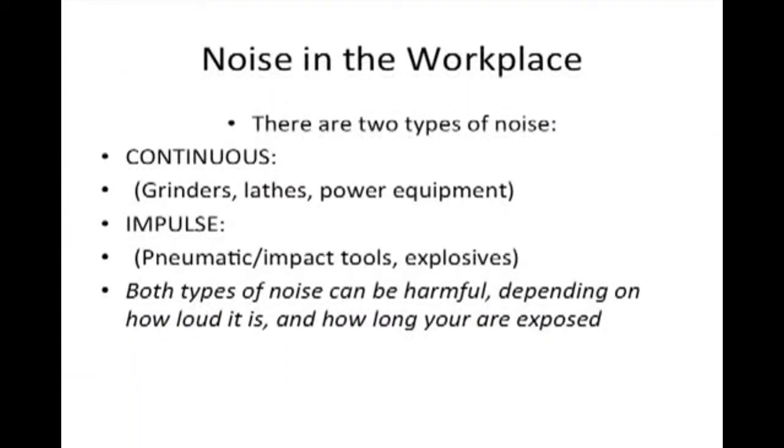As it relates to the workplace, there are two types of noise: continuous or ongoing noise resulting from the use of equipment such as grinders, lathes, or other power equipment. And the second type of noise is impulse noise, or periodic noise, that would result from the use of pneumatic or impact tools or explosives. Both types of noise can be harmful depending on how loud it is and how long you are exposed.